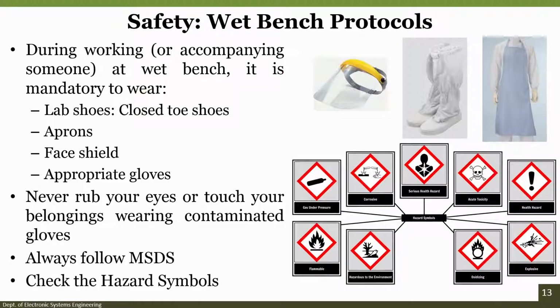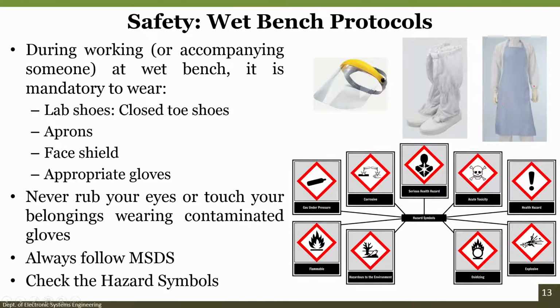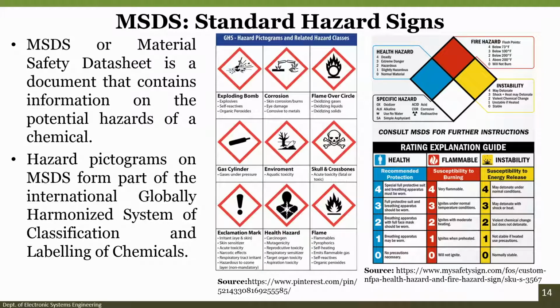So, this is what is shown, a person wearing an apron, face shield, appropriate gloves, before using the wet bench, which is your acid bench. The MSDS, or material safety data sheet, is a document that contains information on potential hazards of a chemical.